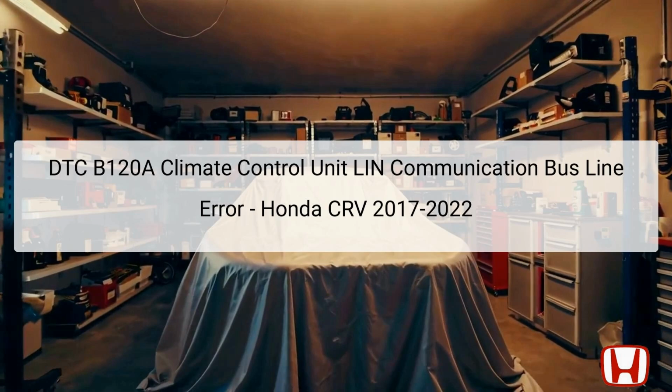The DTC B120A refers to a climate control unit LIN (Local Interconnect Network) communication bus line error. This error indicates a problem within the communication system for the climate control unit, crucial for regulating interior temperatures and managing heating and air conditioning functions in the 2017 to 2022 Honda CR-V.